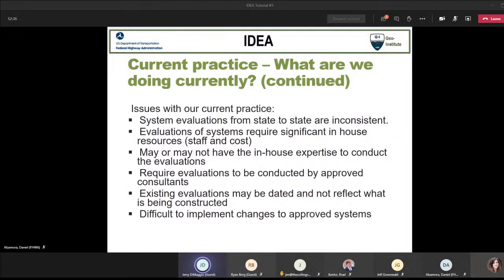So as everybody probably knows, the standard protocol today, which really again began in about the early 80s, was to move from a fully developed set of plans on an individual project design basis to what is commonly referred to as 3-line drawings. When you issue a 3-line drawing with approved systems and then the shop drawings come in for the contractor-selected approved system, it's very common, and I said very common, to where submitted systems often don't reflect what has been approved through the respective approval process.